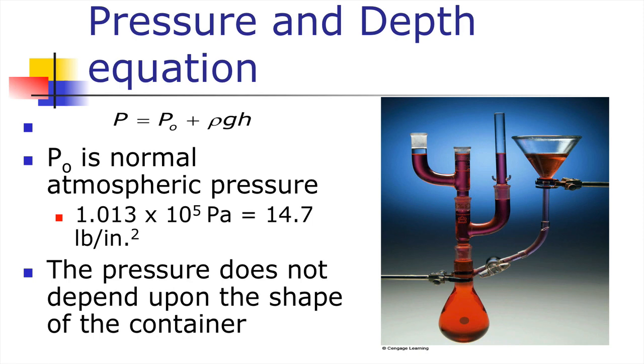So what would be the formula for the pressure that you will experience with height? Pressure is going to be density times gravity times height, depending on the density of the fluid and on where you are swimming from the surface. That is how much pressure you are going to experience. Normally we call this a gauge pressure.